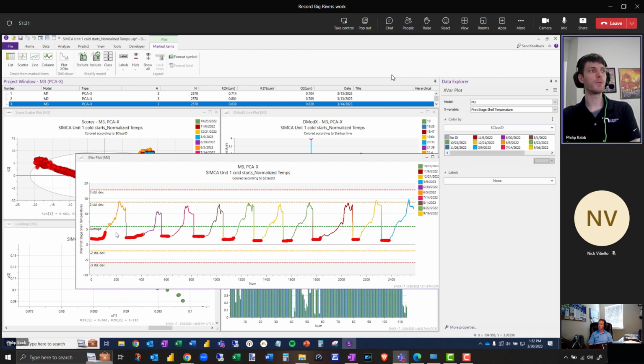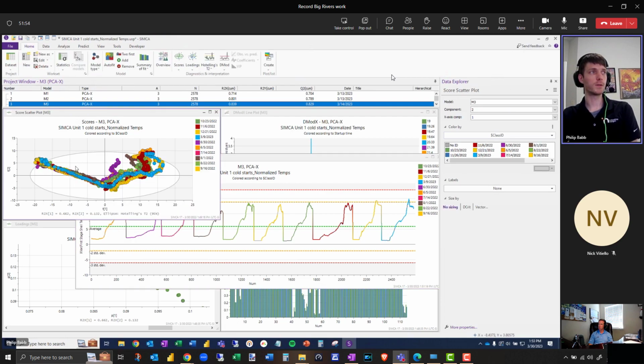All of those initial procedures that they follow, like starting their burners, their igniters, their air heaters, and any other equipment they need to get going, filling up their steam drum, building pressure in the boiler, superheating the steam, all of that stuff is before they begin to heat up the turbine. And from what it looks like on here, that's all pretty similar.